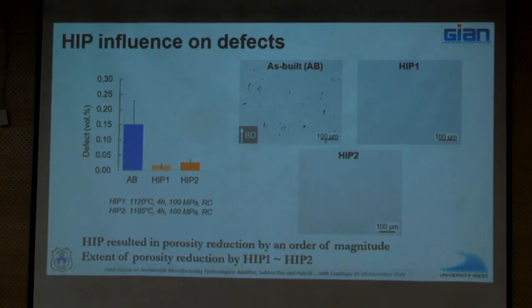In as-built condition, only some of the required phases are formed. But after that it is going to see all sorts of thermal treatment, and the required parent phase may not be formed, which I can guarantee will not form anyway. If you look at a nickel-based superalloy, if you look at how it is put to use, it has to be solutionized, it has to be double-aged, to get the precipitates that we spoke about, right?